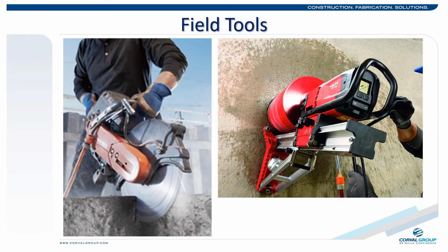This slide shows the options with using a wet method to control the generation of silica dust. The key phrase with wet methods is point of impact. It is not compliant to flood an area with a garden hose and then start breaking or chipping. The water must be applied at the point of impact. That is where the tooling meets the concrete.